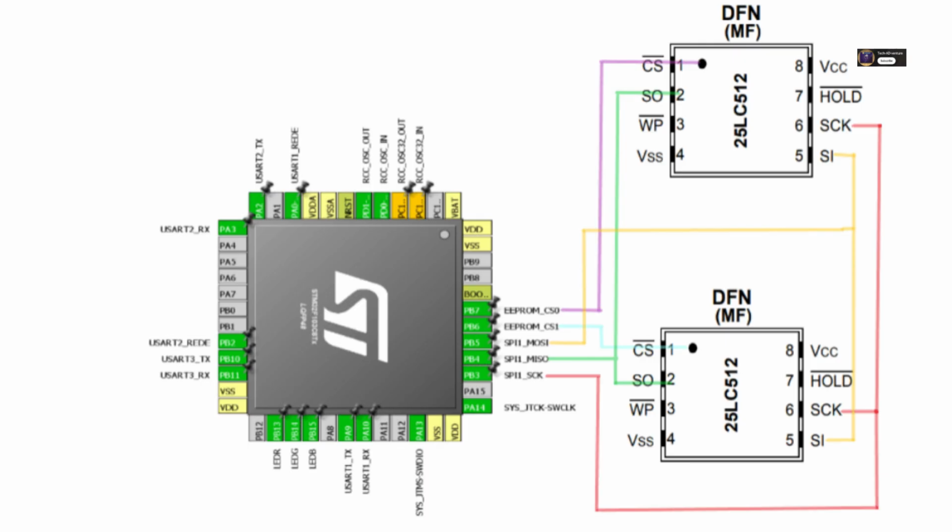And EEPROMs? EEPROMs are simpler here. Usually no separate erase step. You send write enable, then the write command, address, and data. Writes might still take some time internally, so checking a busy status or just waiting a specified time from the datasheet is often needed. And remember that page boundary wraparound thing still applies to EEPROM page writes.